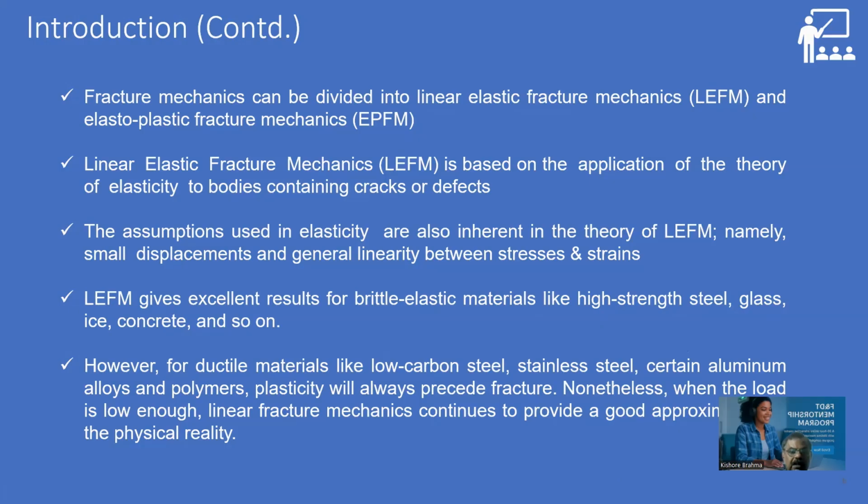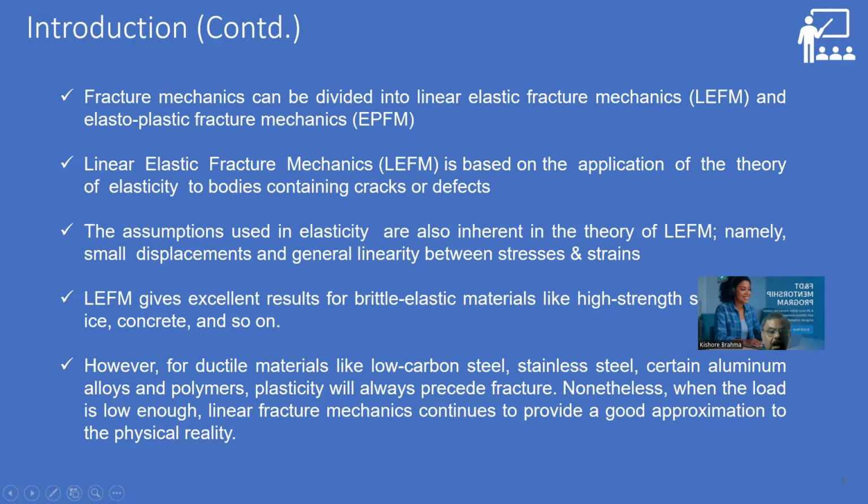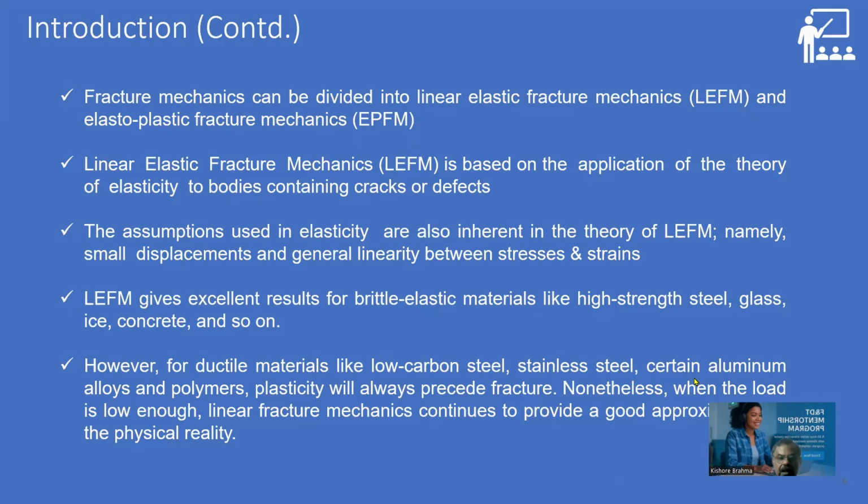LEFM gives excellent results for brittle elastic materials like high-strength steel, glass, ice, concrete, and so on. However, for ductile materials like low-carbon steel, stainless steel, certain aluminum alloys, and polymers, plasticity will always precede fracture. Nevertheless, when the load is low enough, linear fracture mechanics continues to provide a good approximation to the physical reality.